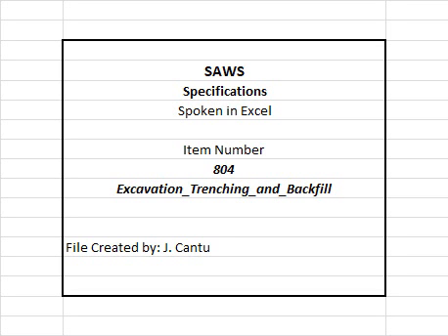E. Establish and maintain temporary drainage ditches and other diversions outside excavation limits. F. Do not use trench excavations as temporary drainage ditches. G. Dewatering devices shall be provided by the contractor with filters to prevent the removal of fines from the soil. H. Should the pumping system draw fines from the soil, the inspector shall order immediate shutdown, and remedial measures will be the responsibility of the contractor.